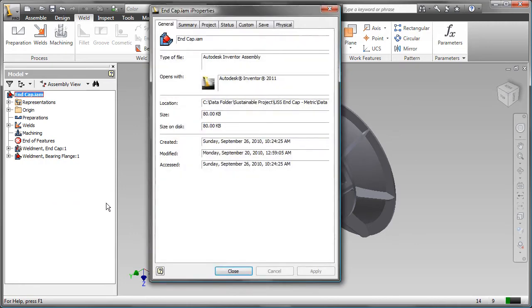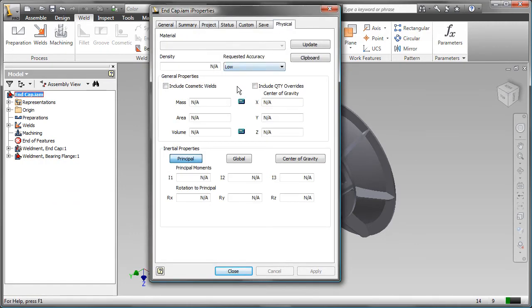But you don't need to stop here. There are ways to make this part even better. As a challenge exercise, try and refine the design even further. Possible modifications include reducing the end cap wall thickness, using 5 ribs instead of 6, changing the shape of the ribs, or even lightweighting the bearing box.